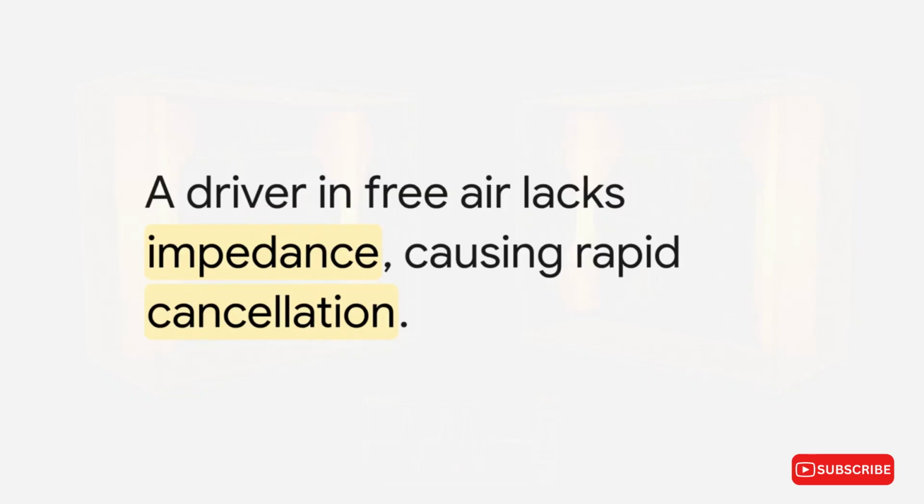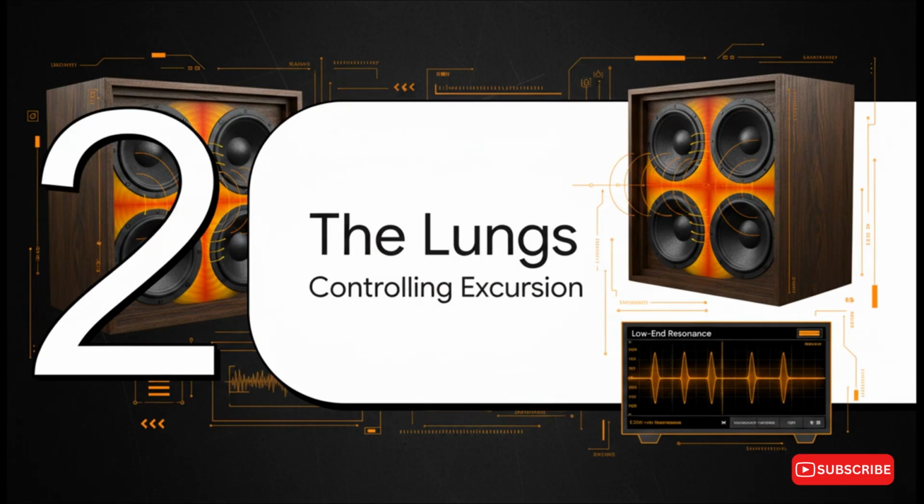It's actually a super common misconception that the driver all by itself generates the tone. It doesn't. If you take a high-quality speaker driver and just suspend it in free air completely outside of a cabinet, it lacks acoustic impedance. What happens is the sound waves coming from the rear of the speaker basically wrap around and instantly cancel out the sound coming from the front. The acoustic result, a remarkably thin, weak sound. So, the cabinet's primary function is to surgically isolate that rear wave, which allows the frontal sound to actually project out and reach you. Let's move on to section 2, the lungs.